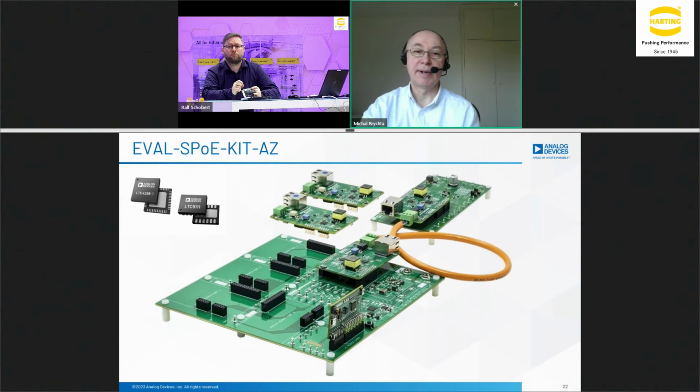You can see the motherboard for the PSE controller. It has 5 channels, so you can plug in 5 modules for data and power coupling. By default, it serves 10BASE-T1L data, but the PSE and PD controller would work with any single pair technology up to gigabit.